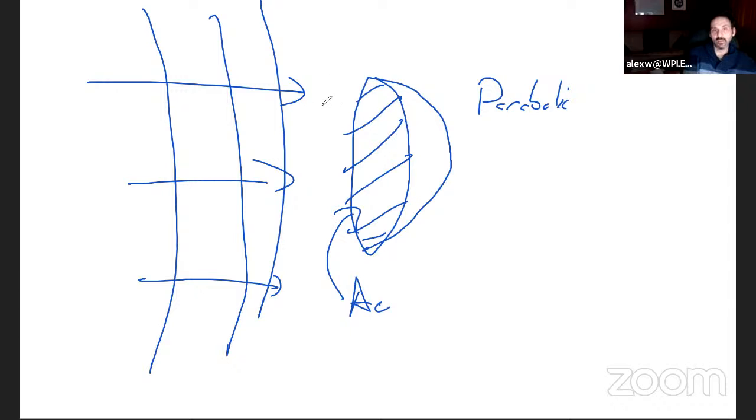One thing to keep in mind: at very, very large distances between transmitter and receiver, the spherical surface that you intercept as it propagates away from the point source can be approximated as a flat surface. If you're close to it, it'll look round, but far away it's flat. So that's how we can assume just the surface area there.